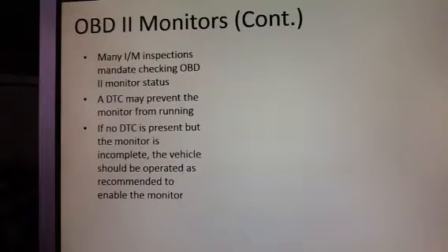If there is no diagnostic trouble code present, but the monitor is incomplete, the vehicle should be operated as recommended to enable that monitor. So we should do whatever we need to get that monitor to the status where it can start sampling and make sure that the vehicle is running properly.